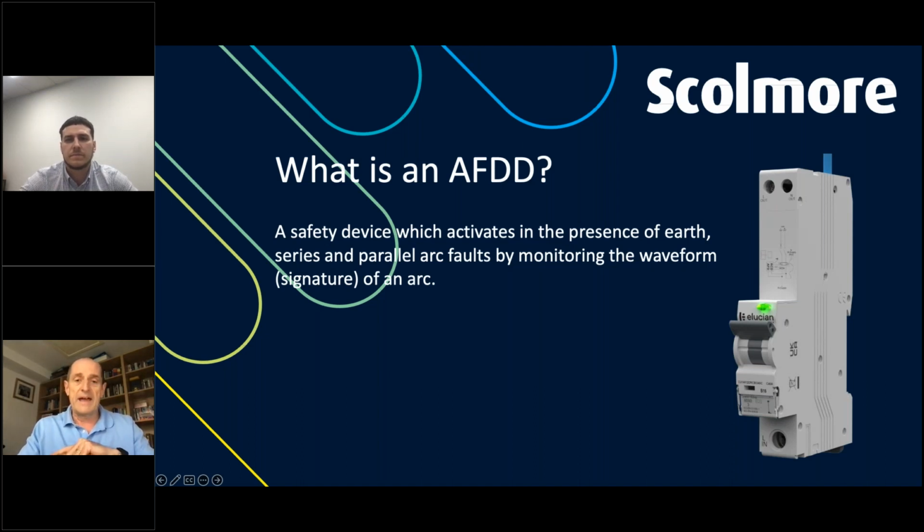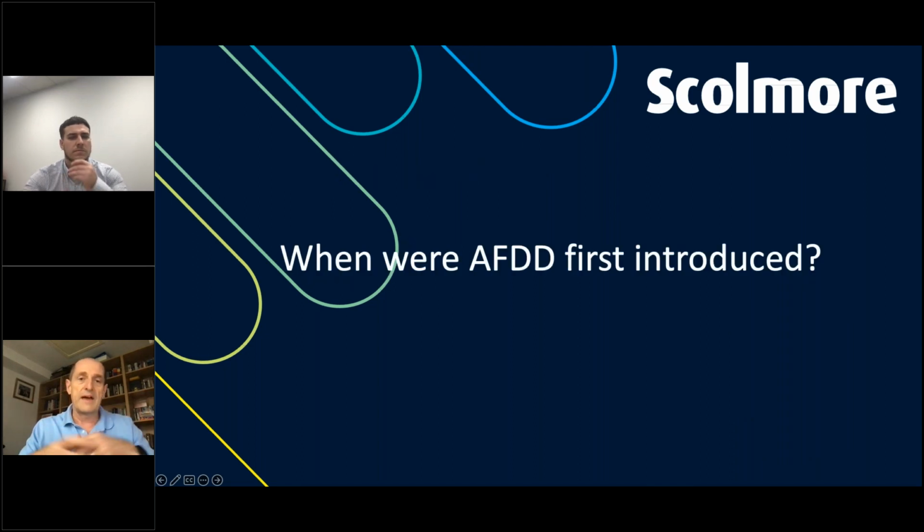It's been a standard that has, in effect, Jake, remained unchanged, but then it's not a very old standard, probably around about 2013, something like that. And so the checks and tests associated with an AFDD are very much locked into AC final circuits, and so on. And they reduce the risk of fire by ignition under certain arc fault conditions.